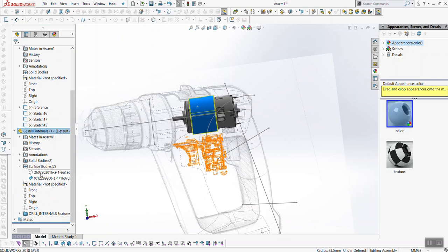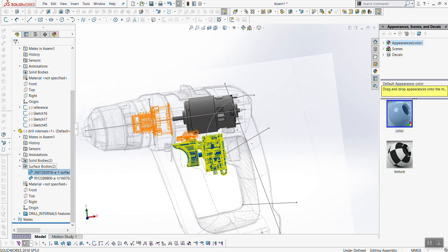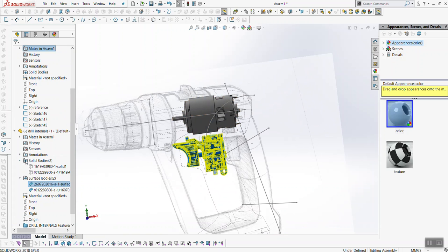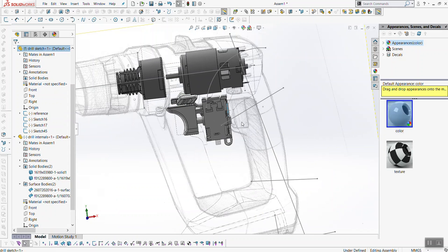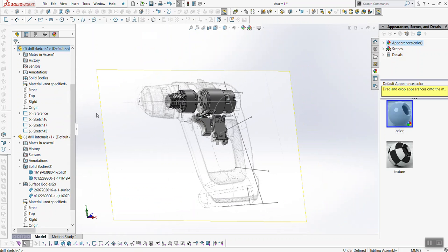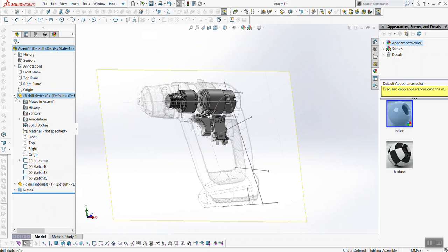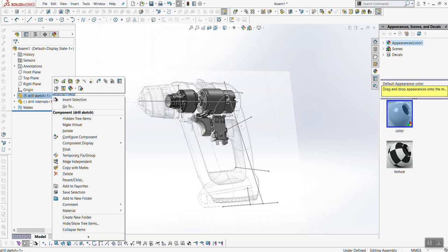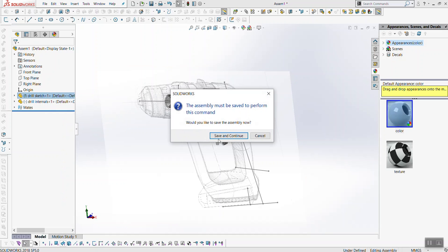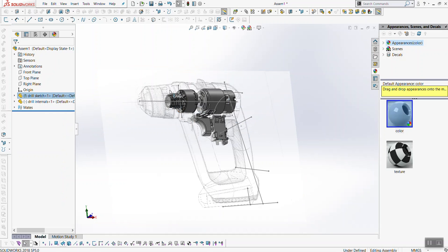And again, you would then repeat this process for each of these other things. So, for the trigger, for the chuck, and so on. And obviously I have this in the wrong place. But now once you have this set up, you could move forward in one of two ways. You could take your master sketch here and again say edit part. It wants me to save.